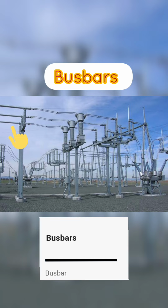An electrical busbar is a metal strip or bar used to distribute electrical power to multiple electrical loads or devices. It is commonly used in electrical power distribution systems, where it serves as a central point for the connection of multiple electrical circuits. Busbars are typically made of copper or aluminum and are designed to handle high current loads. They can be shaped in a variety of ways, including rectangular, round, or hexagonal shapes, depending on the specific application and requirements.